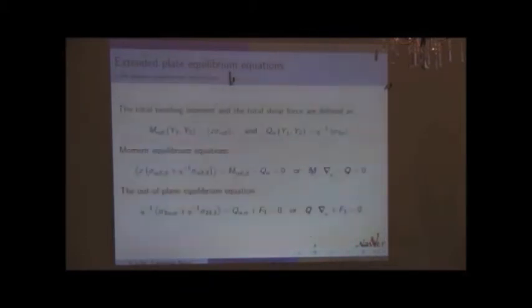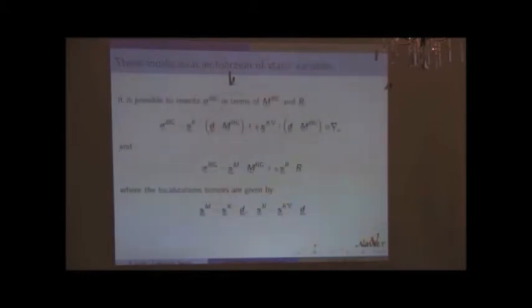The only thing I want to say is that you must notice that if you take the 3D equilibrium and inject this into the 3D equilibrium equation, this is not a completely statically admissible field in terms of 3D. It satisfies the 3D equilibrium equation at a higher order than the Kirchhoff-Love stress distribution.